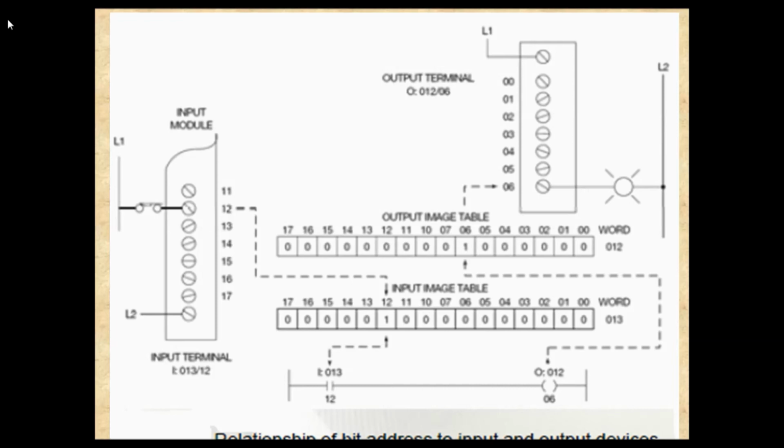Okay, so now let's go look at the output card. So the output card we have here, and our output O, at 12/6. So we have a light coming in here on pin 6. And here we are addressing it. O:12/6 is our output device address.